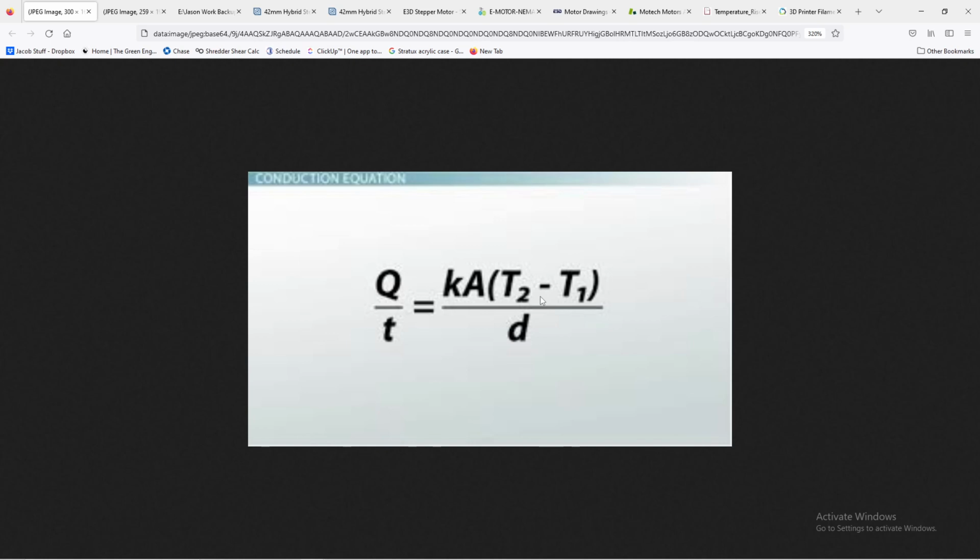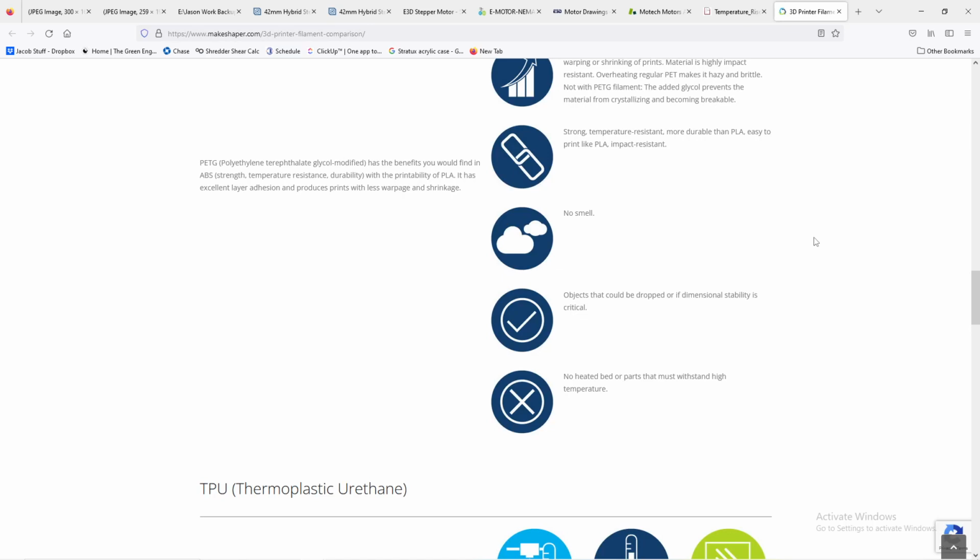As I said here with this first image, these two are already closer together. And so as that heated bed heats up the chamber, it's going to heat up that chamber hotter because these temperature differences aren't as much, and so you aren't going to lose as much heat to the environment from the enclosure, right? Or whether it's an enclosure or not, because like I said, an enclosure at 0C versus freezing versus an enclosure versus no enclosure at 30C is a big difference, right? So you can also pick the time that you print around those high temperature parts of the day, right?